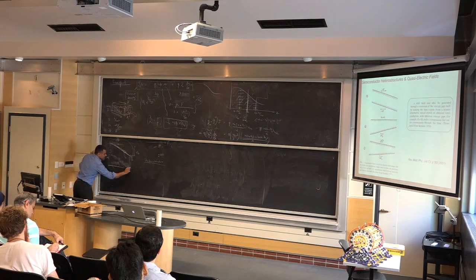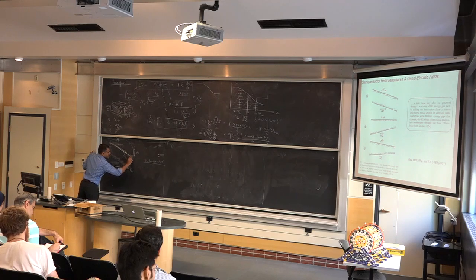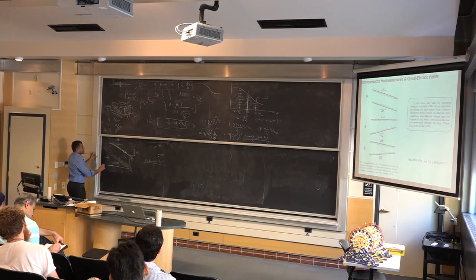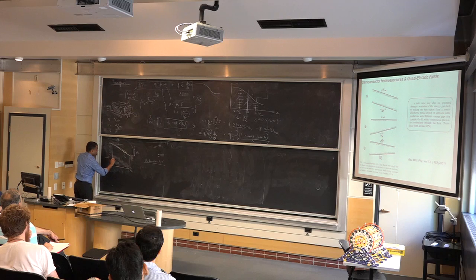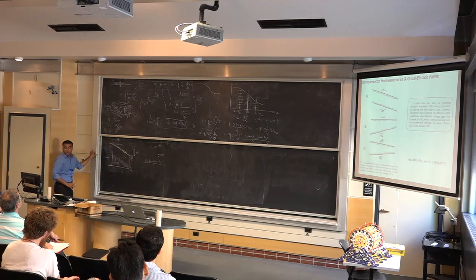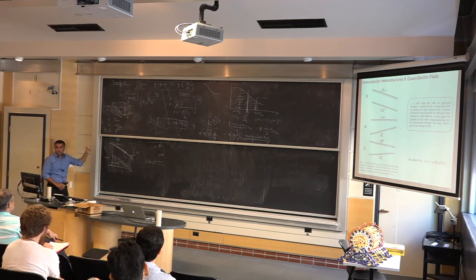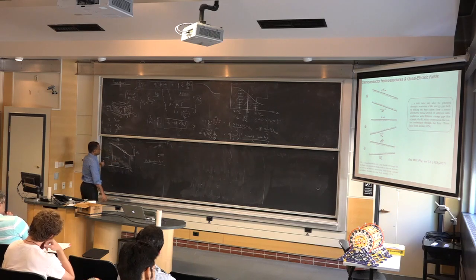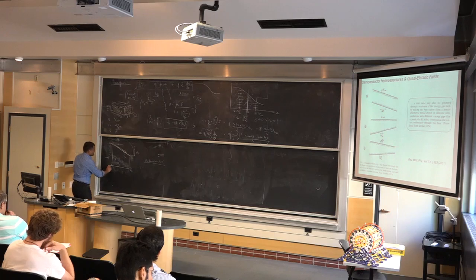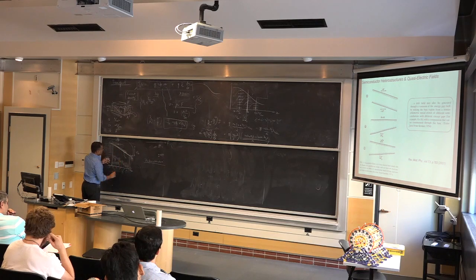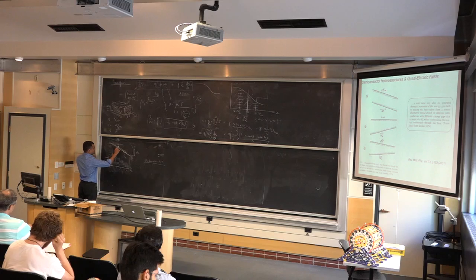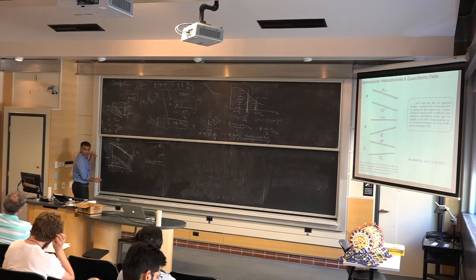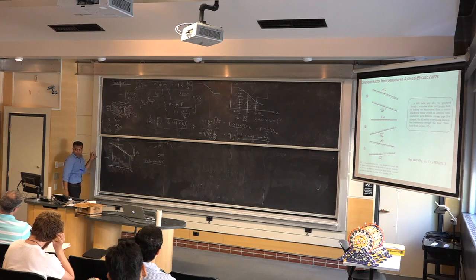Make sense? So this is the valence band edge. This is the conduction band edge. Right? And this is my semiconductor now. I mean, this is the band gap, and the band gap is changing across this material. Does that make sense? So this is called a graded heterojunction semiconductor, and then these states are filled, these are empty. Now you can see that if I release an electron here, it will move to the right. But if I release a hole here, it's not going to do anything.